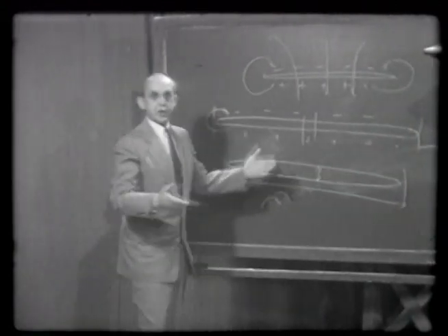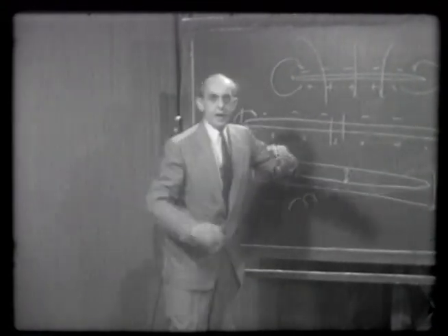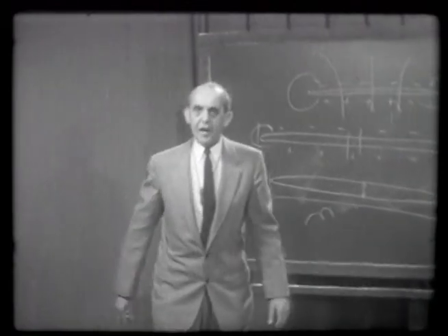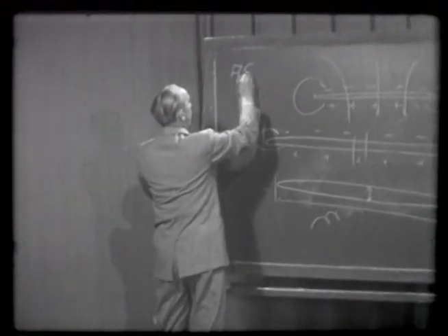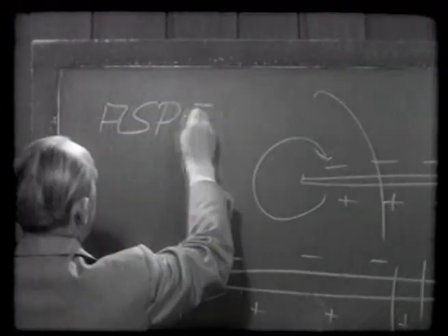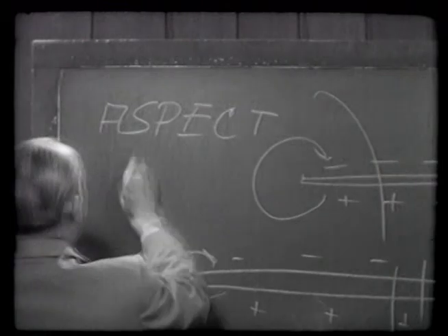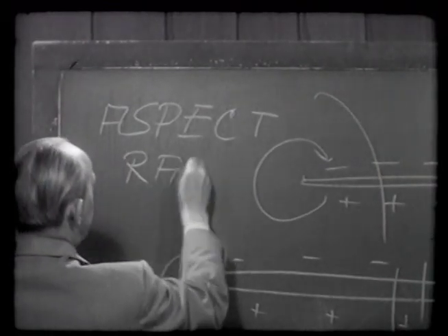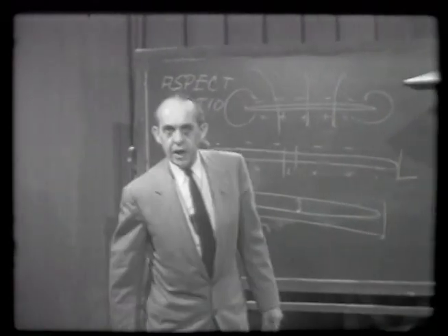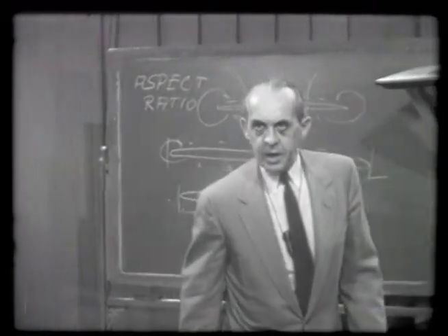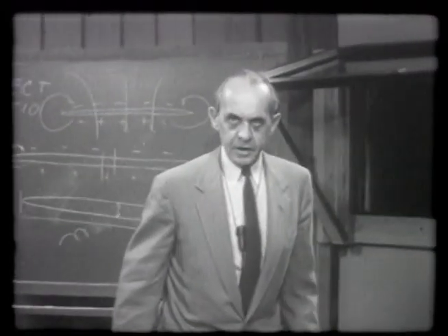And this ratio between the span and the mean chord of the wing, we call it the aspect ratio of the wing. You might hear it very often when people talk about it, aspect ratio. And you see that aircraft for high flight economy have high aspect ratio.